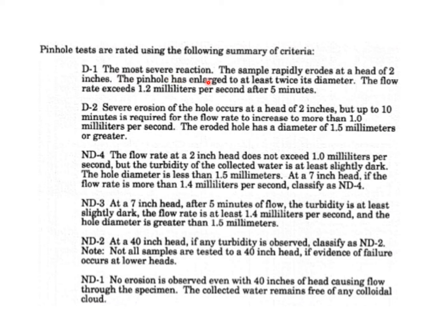The sample rapidly erodes at a head of 2 inches. The pinhole has enlarged to at least twice its diameter. The flow rate exceeds 1.2 milliliters per second after 5 minutes.